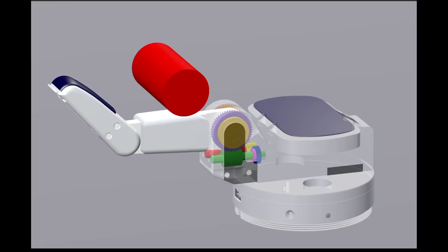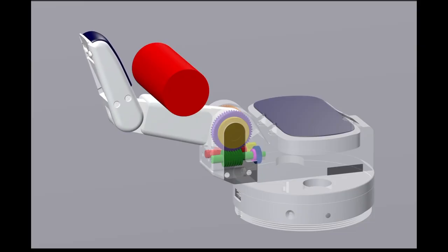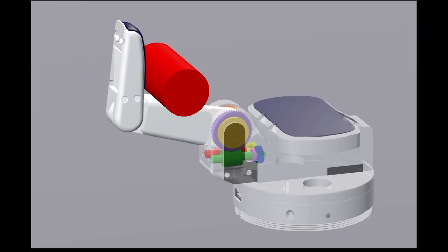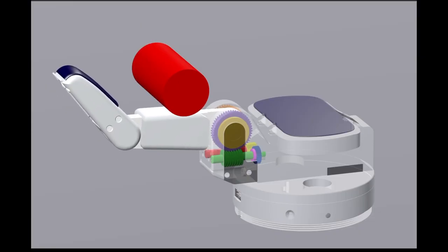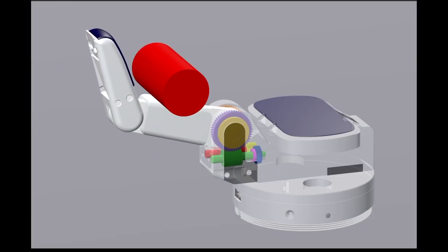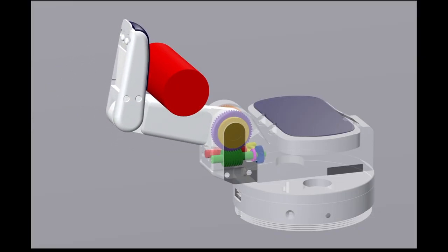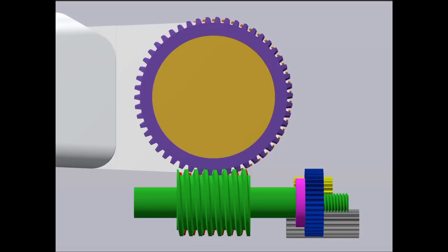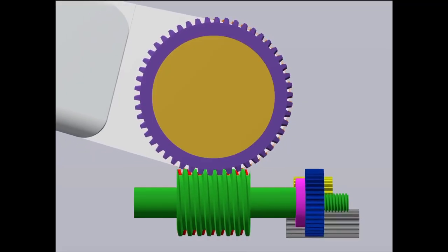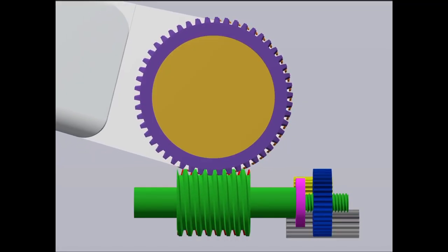The predictive capabilities of the method are demonstrated by simulating the unique gearing mechanism of the BarrettHand, which relies heavily on friction and stick-slip transitions. In this system, a single motor drives both the proximal and distal links of a finger through a coupled gear arrangement. The proximal gear rides freely on internal threads along the shaft of the adjacent worm gear, with Belleville washers at the end acting as a clutch.